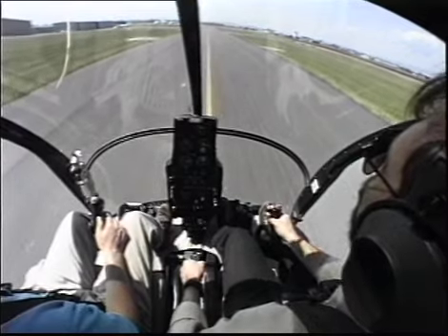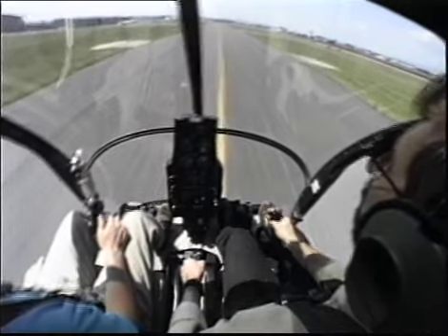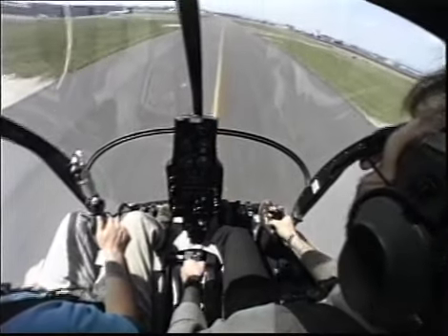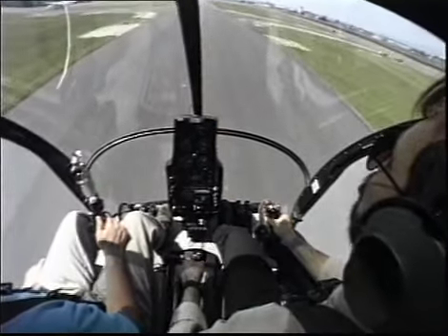The dangers usually associated with a running takeoff and running landings include main rotor contact with the tail boom, ground resonance, and difficulty in maintaining directional control. Running takeoffs and running landings require a surface of sufficient length and smoothness and that present no barriers to a shallow climb or approach.